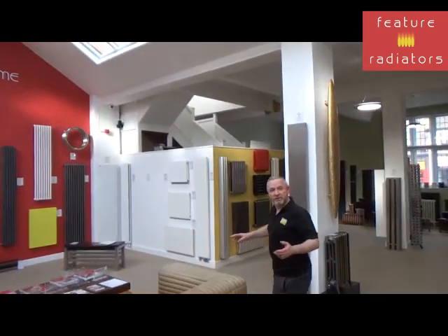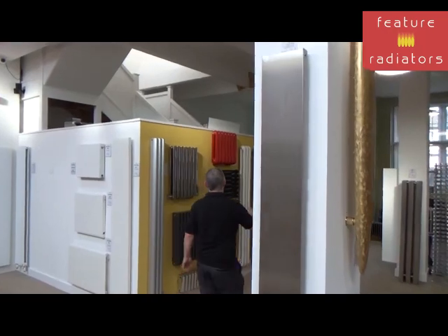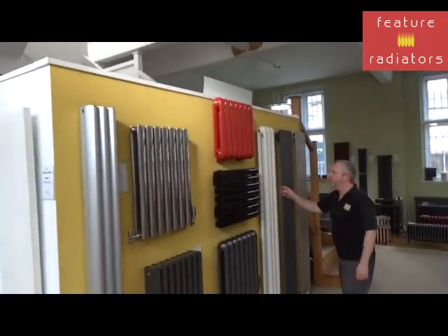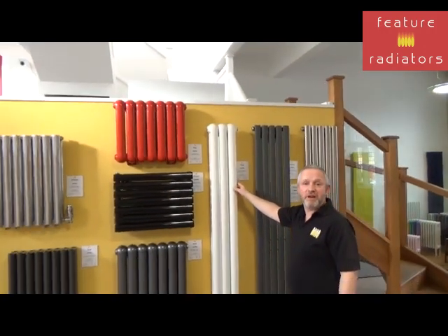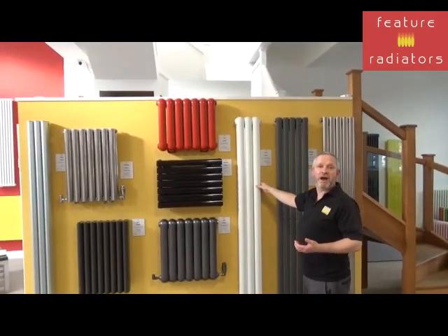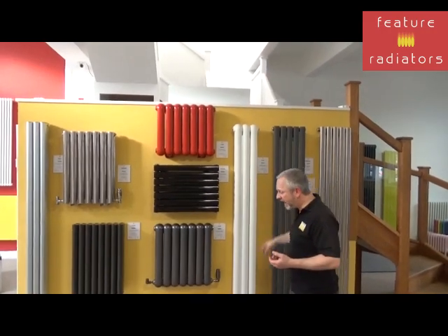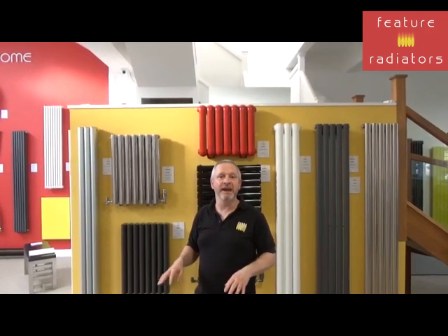we've got an example of a 3-bar pod radiator. If we look at this one, it provides an output of 1165 watts, so that's a lot closer to the requirement, and you might opt for that one. Now, we won't worry about providing a radiator that gives you more heat output than you require, because at the end of the day, once it's installed, if it's not right, you can't turn the radiator up any further. But if you've got more than you need, you can put a thermostatic valve on it to keep it regulated and you're still keeping your radiator efficient.